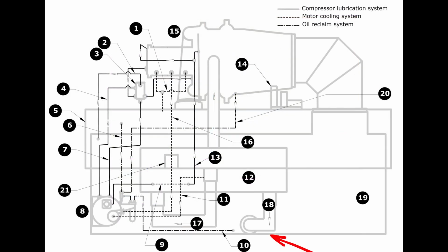That helps us maintain a proper flow and efficiency across the whole evaporator. And that's what you see here. So this is the inlet port for the evaporator. Now, that being the case, this can vary in its location. My point is, be cautious in some of these graphics that show it right here at the bottom. That's not always the case.